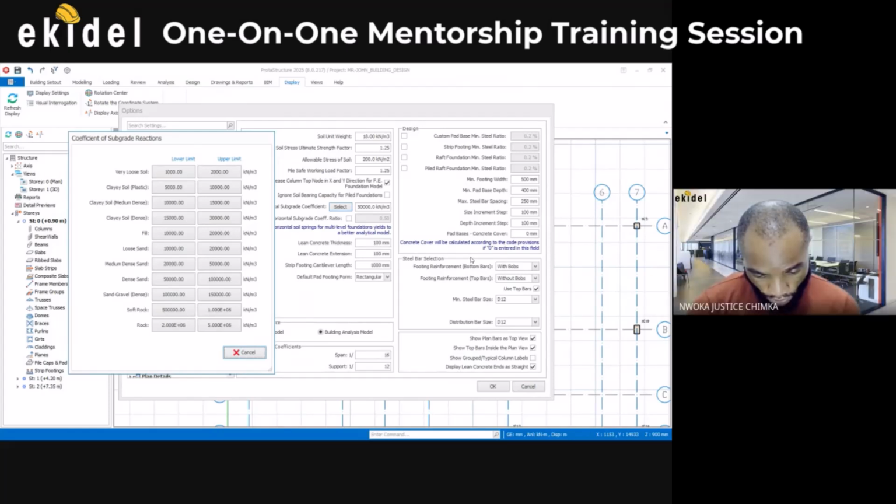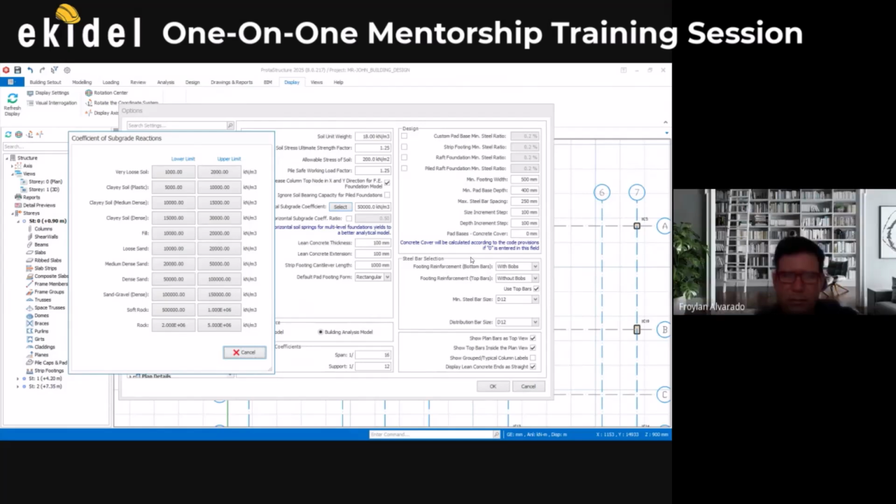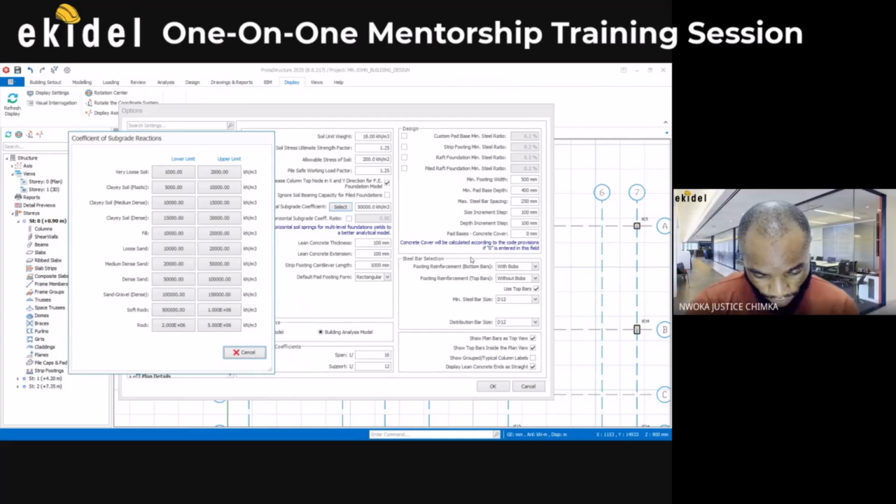Then on this place now, they are saying the allowable concentric service load in tons. They have 86, 89, 129, and all that. Although this links to the sizes. So I think that falls between 12 and 14. So either first of all try 12, then if it doesn't work well, then try 14.